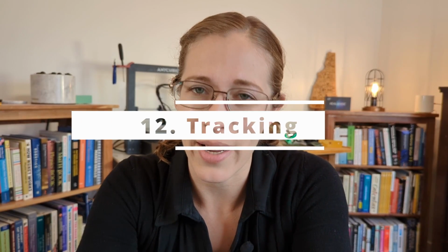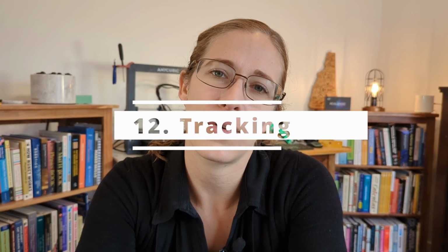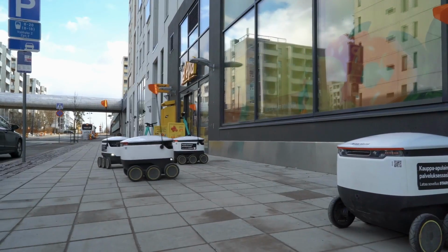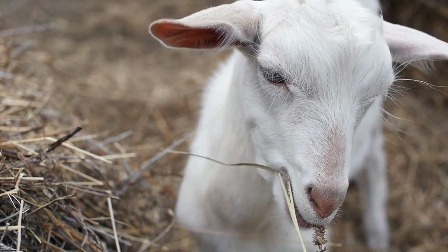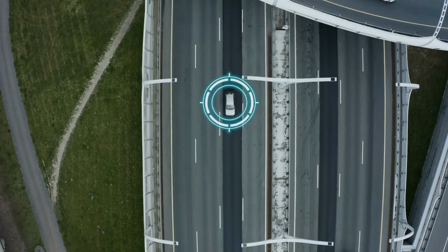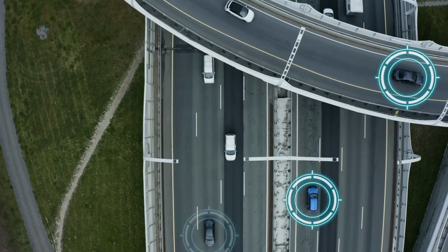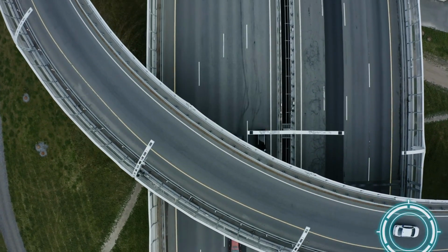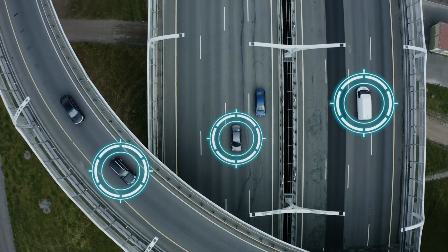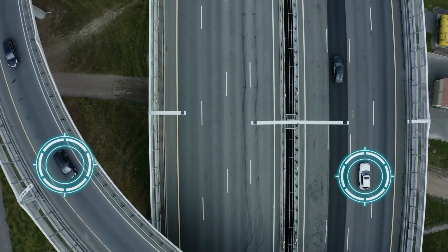Next, we're getting into the tracking problem. Generally you want to use tracking either for avoiding something or for monitoring something. Tracking I've worked on quite a bit. You want to detect the object, which may be on the perception side. You'll have all of your objects for each frame coming in, and you may have different stages of association. If you need to establish velocity, you may need to do frame-to-frame association with a certain sensor prior to it going into sensor fusion.